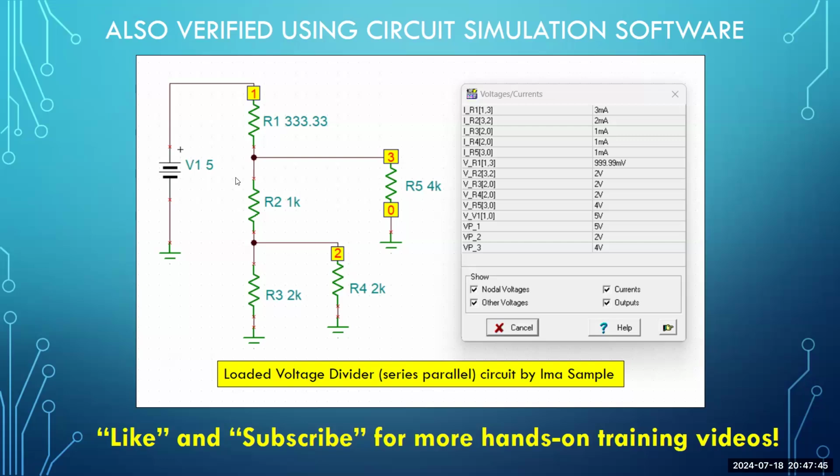By popping our calculated values for these resistances into the simulator, we would be able to see the measurements and that they do in fact jive with what we want. So the current through R4 needed to be 1 milliamp. So look up IR4. IR4 is right here on this row, and it is 1 milliamp.